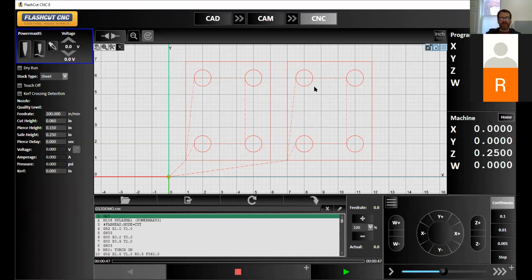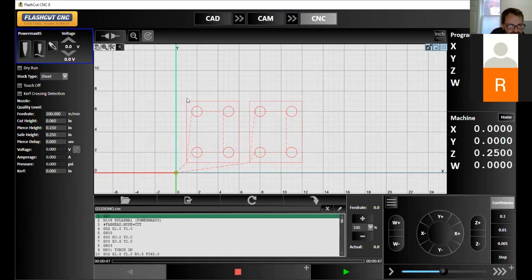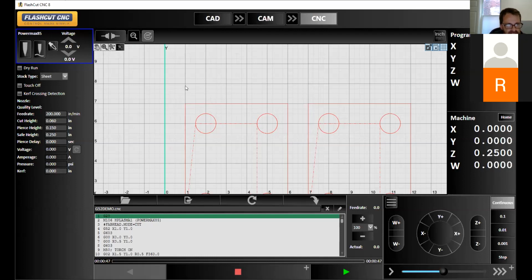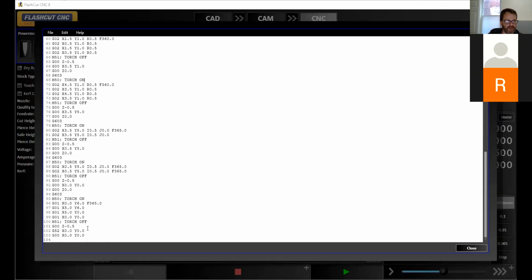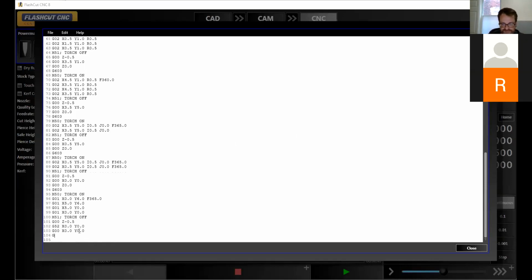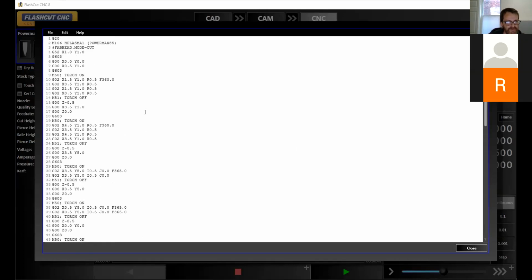No. Okay, in the notes that I send, I actually do a comparison of the computer-generated G code versus the G code that I wrote with the G52 addition, so I could put it in the proper place. Let's say we want to do another one at X1, Y8. You can continue this forever. G52, X1, Y8. Copy everything from just under our first G52.